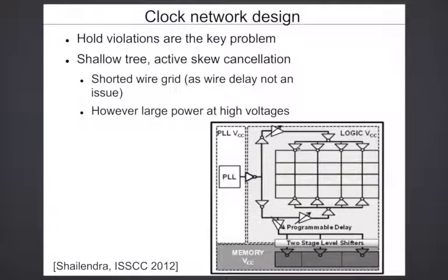But as I said, you can have two paths, one path having 2 logic cells, another path having 1 logic cell, and both the paths are shorted, and you can control the weight between the two in some sense, kind of like the mixing we are doing out here to adjust the delay. So there are many different topologies for adjusting the delay, and also to adjust delays at sub logic cell delay resolution.